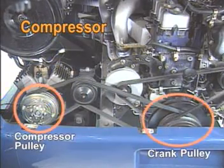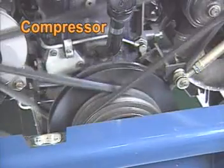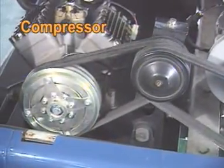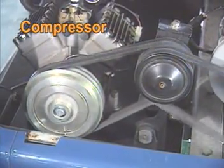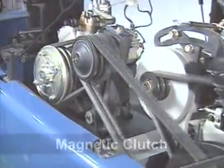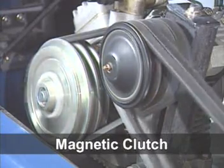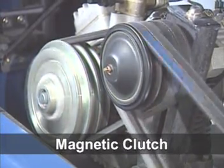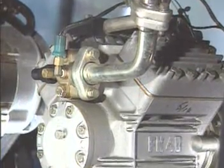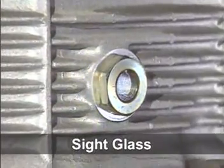The compressor pulley is connected to the crank pulley by a V-belt, and the V-belt delivers engine power to the compressor. A magnetic clutch is installed at the compressor pulley. The magnetic clutch turns on and delivers engine power to the compressor when the air conditioner is on. A sight glass is installed on the compressor block to check the lubricant oil quantity.